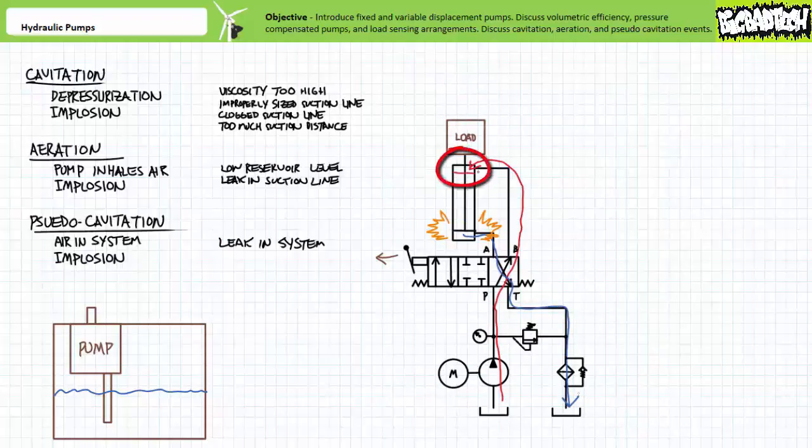Note as the piston rod end face rips away from the liquid still in the rod end. This is a rapid depressurization event, and the oil can enter the vapor phase. As pressurized flow entering the rod end catches up, oil in the vapor phase is rapidly repressurized and implodes. Not only did the lifted weight crash to the ground uncontrollably, a cavitation event occurred in the cylinder. If this is a recurring event, lasting damage may result. We'll examine flow control methods and counterbalance valves in later lectures that permit not only the controlled descent of a lifted object, but also prevent cavitation from occurring.